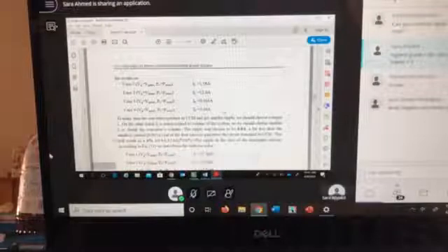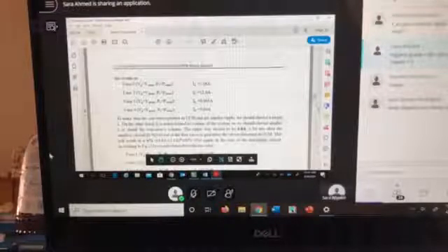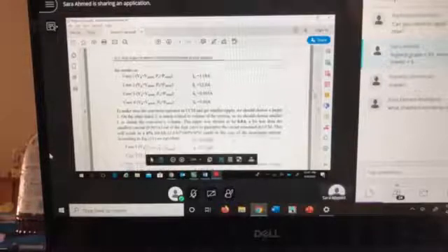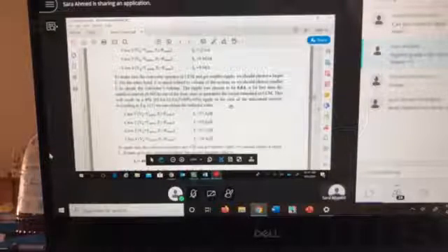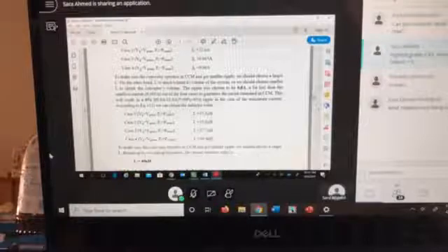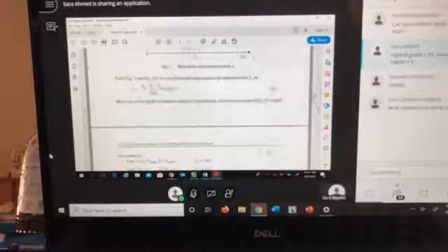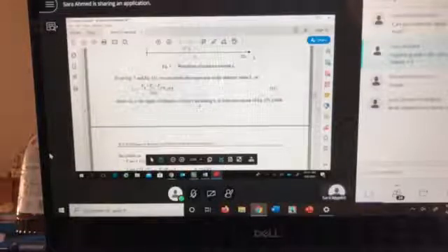So in this case, when we chose this 0.8, it resulted to be 6% of your maximum current because your maximum current is 12.6. Which is okay. It might be less than usually what they use, 10%, but it is okay because you are guaranteeing that you are in that value. Once I have delta IL, then I basically have everything that I need in this equation of the inductance. So I solve for it.